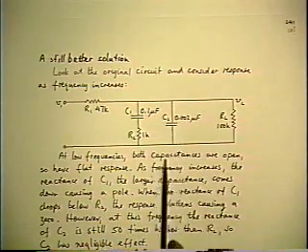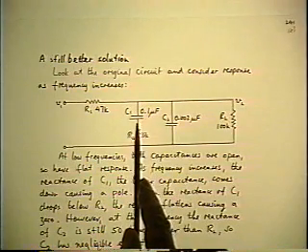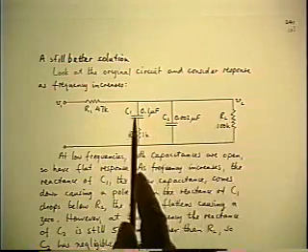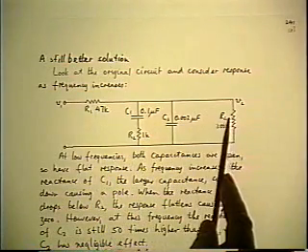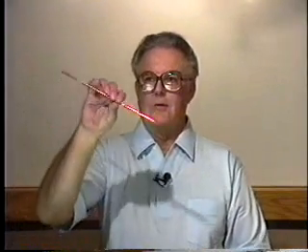So forget C2 while the reactance of C1 comes down. Now, as it comes down to be comparable with R1 and RL, of course, it's going to start bypassing the RL, so the 0 frequency flat gain is going to start dropping off. So there's going to be a pole somewhere because of the C1, C2 being negligible.